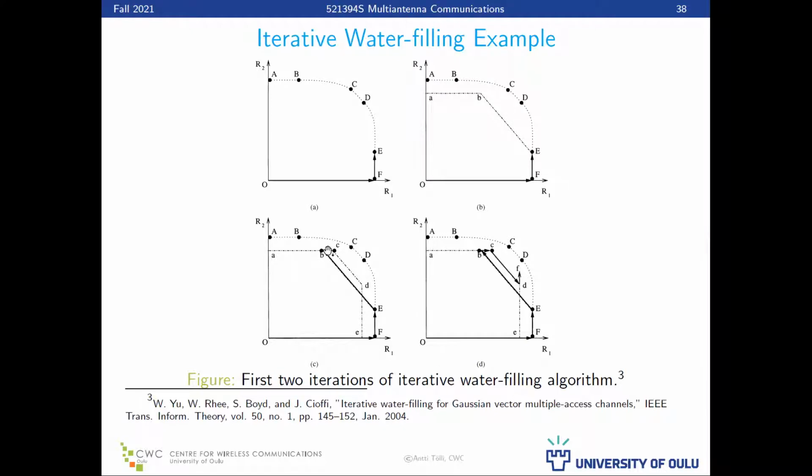You move from this point to this point. Then you switch the decoding order to this point. You optimize the transmit covariance matrix of user 2 given the re-optimized Kx1, and so forth, right? So you just move gradually until you reach the sum rate region. Yeah, makes sense?